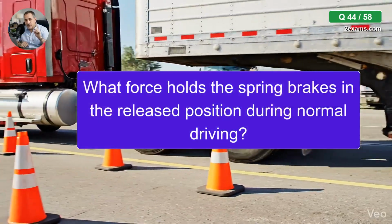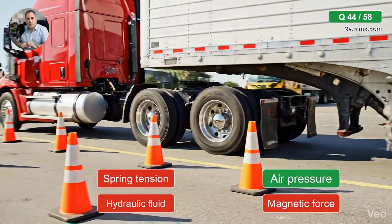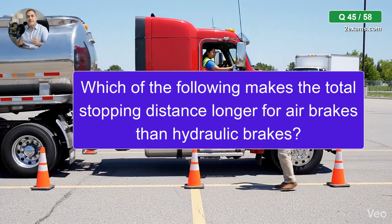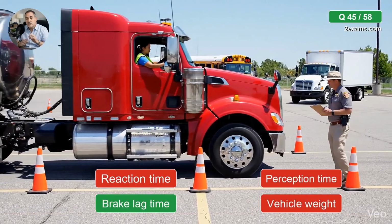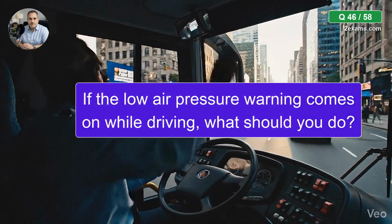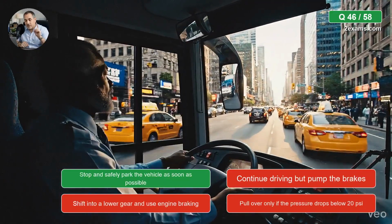What force holds the spring brakes in the released position during normal driving? The correct answer is, air pressure. Which of the following makes the total stopping distance longer for air brakes than hydraulic brakes? The correct answer is, brake lag time. If the low air pressure warning comes on while driving, what should you do? The correct answer is, stop and safely park the vehicle as soon as possible.